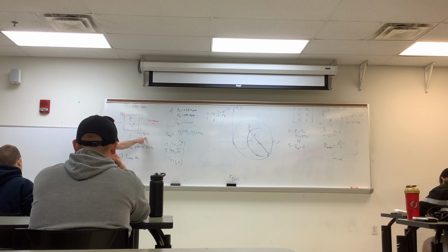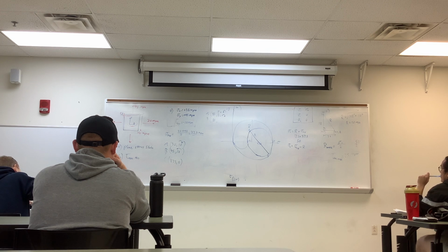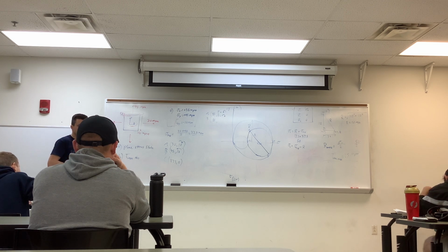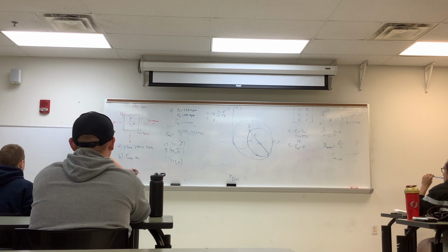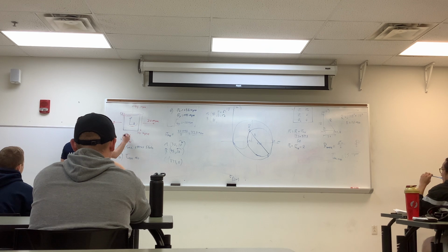The way I'm able to see it is in quadrants: 1, 2, 3, and 4. If it's pointing toward the second and fourth quadrants, then it's negative, and if it's first and third, then it's positive. That's just for the shear. Everyone has their own way of visualizing it. That's the one that helped me the most. So if our x-axis was in this direction, and our y was still vertical, this shear would then be positive.